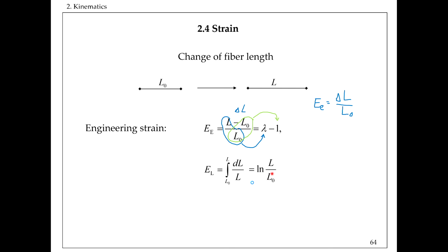All right, so this is very strange. We can also write it in terms of the stretch ratio, because L divided by L0 is exactly lambda, the stretch, which is the parameter that says how many times the initial length changes, going from L0 to L. So we can call it lambda exactly as we did here.